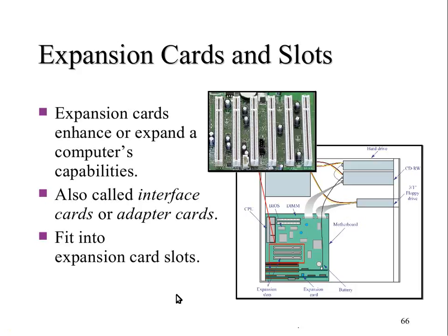Now what happens when you turn on your computer? An important thing to know about is how your computer behaves when you first turn it on, because a lot of times problems with the computer show up when you first power it on. The first thing, when you turn on your computer, is the power supply comes on. It takes a few moments, maybe a second or two, before the voltages on the power supply are correct, because it has capacitors that charge up.